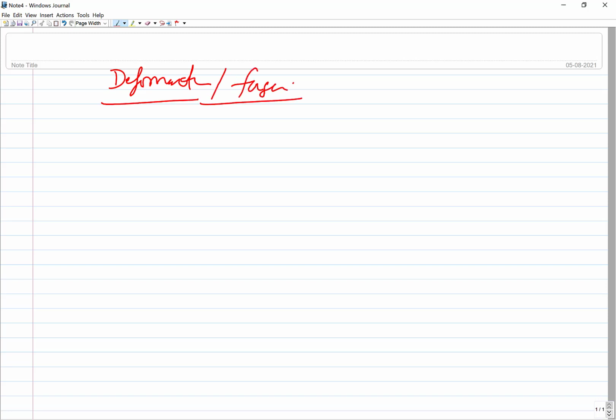In case of deformation, as I said, you perform the joining in such a way that micro level deformation at the interface takes place, like in ultrasonic welding or explosive welding. Here micro level deformation leads to mechanical interlocking, but the intermingling and mixing of the metals from the two sides takes place to such an extent that metallurgical continuity is established across the interface.